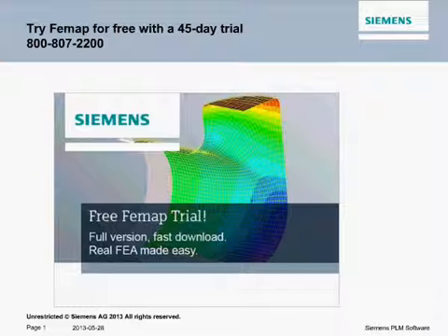There's a few other questions that I noted. One was, will the software simulate water flow from a fire sprinkler system? FEMAP has an optional module called FEMAP Flow, which can do CFD-type problems. It's primarily targeted towards electronics cooling applications, but it can handle different types of liquids and gases. So depending upon the type of system you're trying to model, there is that solution with the FEMAP Flow module.